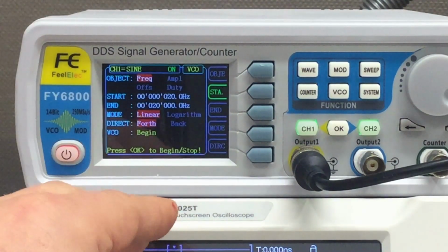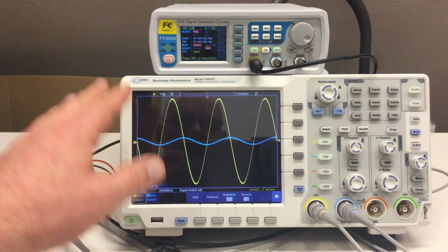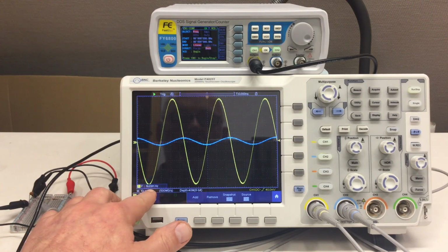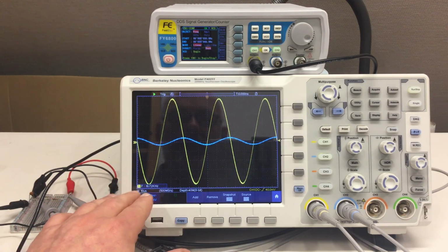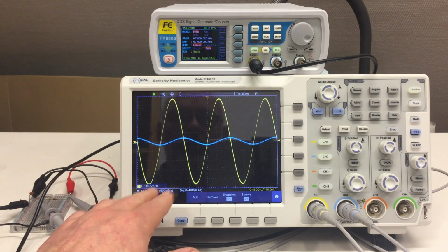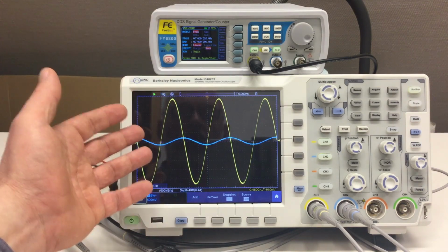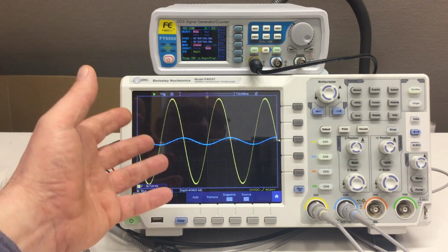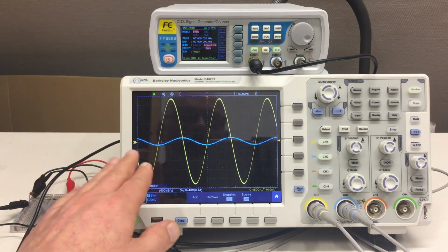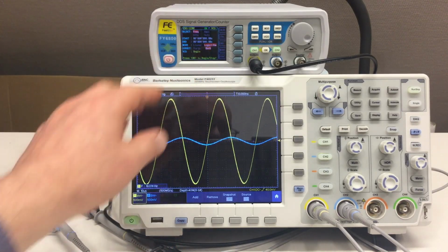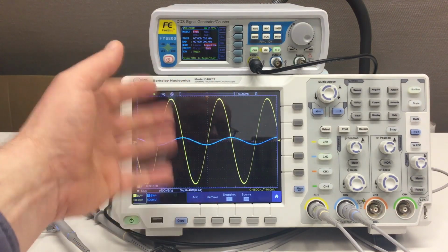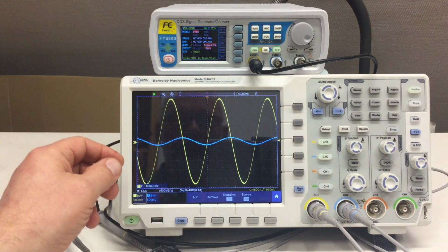Let me experiment a little bit. If I start the sweep from the back, again, I have 19.7 kilohertz instead of 20 kilohertz. So, 19.72. So again, 280 hertz offset. And that doesn't get better if I switch the mode to logarithmic. That is logarithmic frequency increase or decrease on the input voltage.